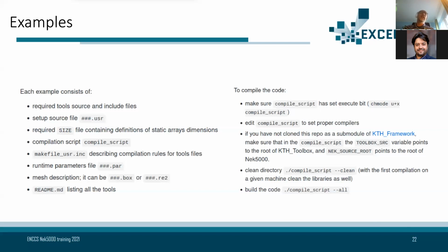In some cases, there can be some additional interfaces required. Like in the case of the statistics tool, you'll also have to provide an interface that tells the code where the span-wise direction is in your mesh and domain, and how it is supposed to perform the span-wise averaging, in the case where you go from 3D to 2D span-wise averaged.